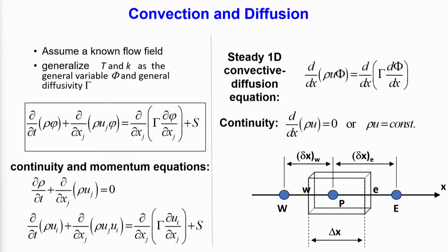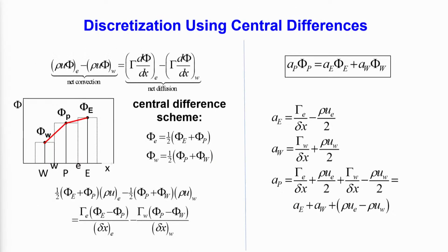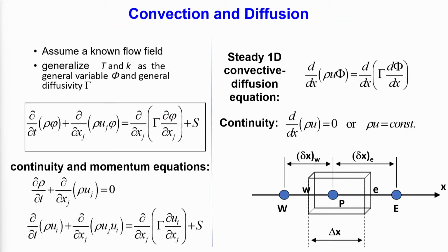And the continuity equation also along x, if you have that, you will have d/dx of rho u equal to 0. There is no y or z variation. So, now with this we will try to see that if we want to discretize it, what we would do. So, look into the previous slide. What would you do? Your step 1 is to integrate the governing differential equation over the finite control volume. This is the first step of the finite volume method.